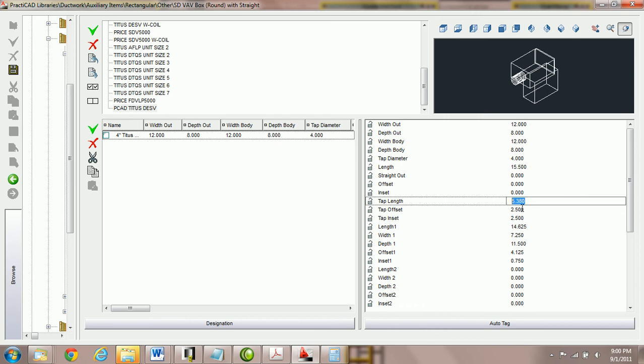Right now we've got our AutoCAD format set to decimal, and we have the precision set to 3 zeros. This allows us to type in values like 5.375. If in fact my format was set to decimal and my precision was set to 0, we would end up getting rounded numbers when we typed in 3 digits. That's why when we go to create catalogs, it's important to change the format and precision. There are instructional videos on that. You go to the AutoCAD menu, format, and change the units there.